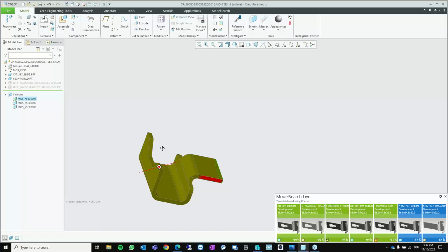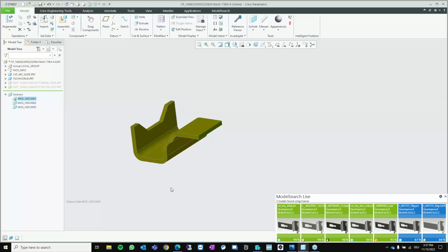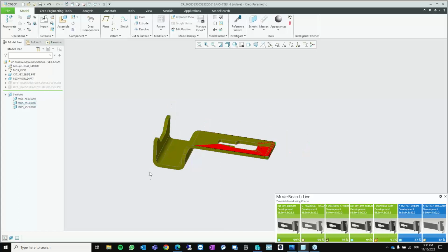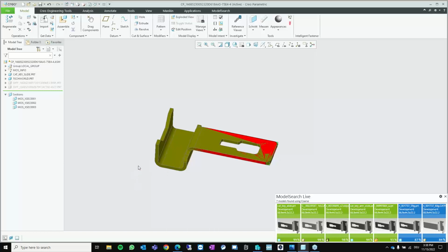As this is a visual analysis tool only, you probably also need to figure out volume or geometric differences of inside surfaces. Well, it's probably not that interesting with the sheet metal model, but imagine you have compared two molded models or two turned models, then it absolutely will make sense. Once more, it's a native Creo Parametric assembly. If you need additional cross sections, feel free to add them, feel free to change existing ones.